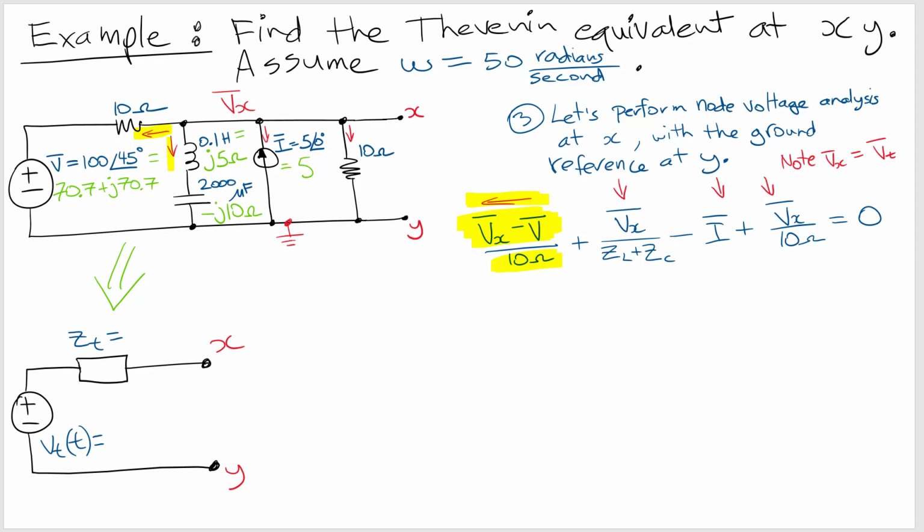So then we go down, the first one going down through the inductor and the capacitor. That's this one in the equation here. The voltage we're starting off with is Vx, and we're going to the ground reference, so the other side is 0. We're not going to write minus 0, so it's just Vx on the top. Then we write the impedance in that branch.